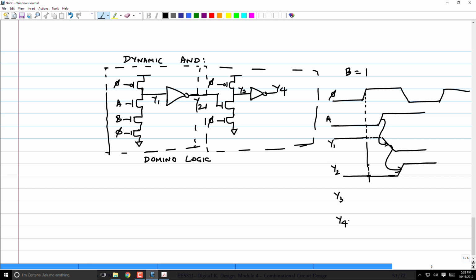No, I agree. But like he said, right, there is one pull-up path. See, now there's a leakage path to VDD also. PMOS is off. NMOS is also off. So there is one pull-up path to VDD, pull-down path to ground. So these two will cause it to come and settle slowly at some point. It can't go below that. You get the point? It is floating, yes. So it can't be at VDD always. But what's the final value? Final value is there is an off PMOS, there is an off NMOS between VDD and ground. So these two leakage currents have to be the same because it's a series path.